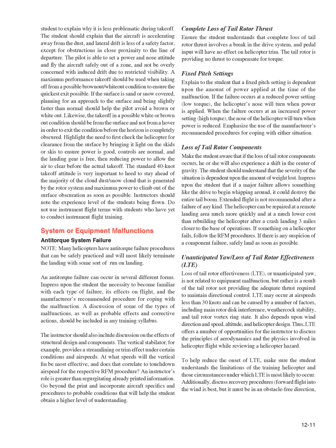System or equipment malfunctions. Anti-torque system failure. Note, many helicopters have anti-torque failure procedures that can be safely practiced, and will most likely terminate the landing with some sort of run-on landing. An anti-torque failure can occur in several different forms. Impress upon the student the necessity to become familiar with each type of failure, its effects on flight, and the manufacturer's recommended procedure for coping with the malfunction.